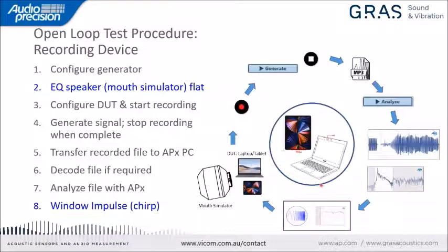We are going to measure the response of the microphones of the laptop or the tablet. We configure the generator, then we EQ the speaker. We are going to use a mouth simulator for this test, and remember, we have to equalize the mouth simulator so it has a flat frequency response before starting the test.